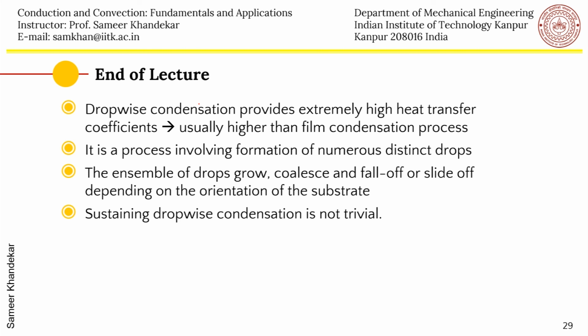And in dropwise condensation, we have only noted the nuances and characteristics, and the fact that dropwise condensation heat transfer is usually one order of magnitude larger than the film-wise condensation process. It is a very important heat transfer process in power plant engineering, for example in nuclear energy, in metal purification processes, and so on. So this is something which is quite prevalent in the industry.